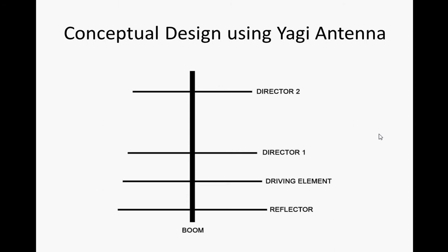As you can see, it has three main elements: the reflector, the driving element, and directors. The driving element is connected directly to the feeder, whereas the directors are coupled to the transmitter power through local electromagnetic fields which induce currents in them. The director elements are cut shorter than the driving element, which itself is a little shorter than a half wavelength at the design frequency.